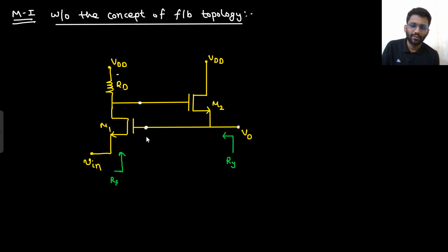Okay, so if this is V0, V0 is coming here. I have already shown this derivation. So what will be this current? This current would be gm1 (Vin minus V0) in the upward direction. Till now you must be comfortable with the small signal analysis. So the drop will be in this direction. So what will be this potential? This potential would be gm1 RD (Vin minus V0).